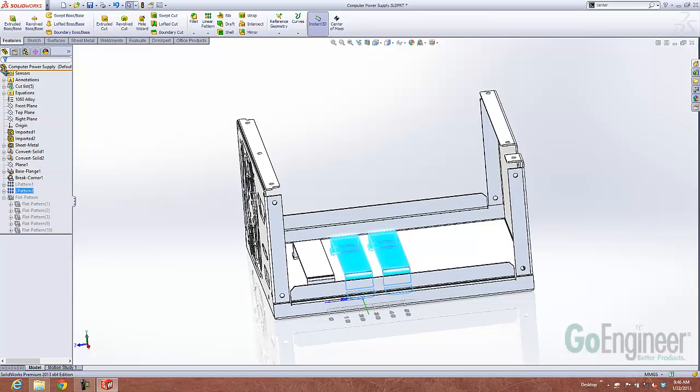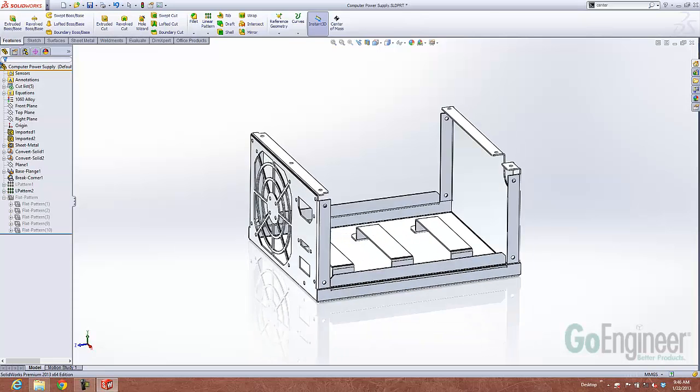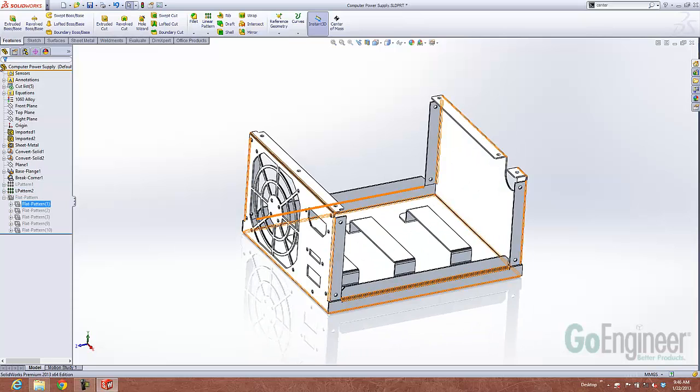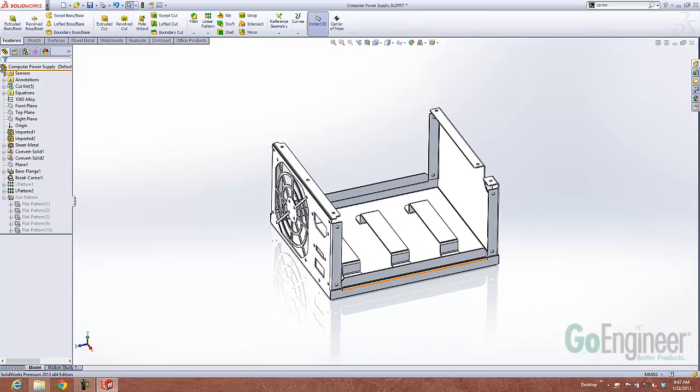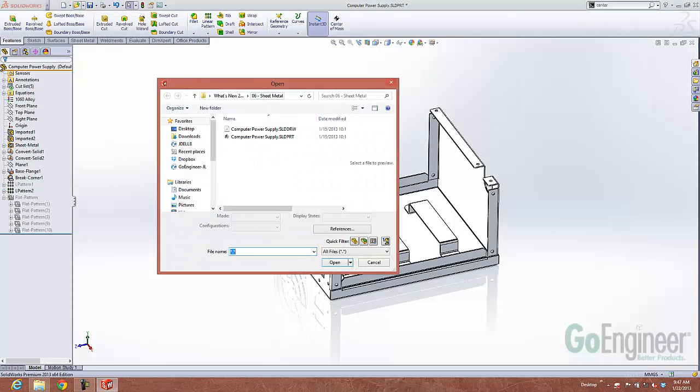In this particular case, I want to make those a little bit bigger, so I'll just use my drag tools, eyeball that in here, and then use my ruler to snap them in at 50 millimeters apart. So a couple little things there, the feature manager specifically, and hopefully you guys know about the ability to just take those dimensions and drag them around to get to exactly where we're looking at. Now, as far as form tools are concerned, we have the ability now to apply what we call a, I can't think of the word now.